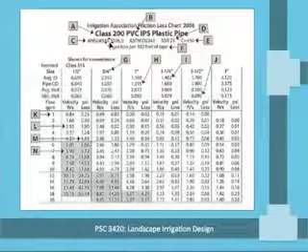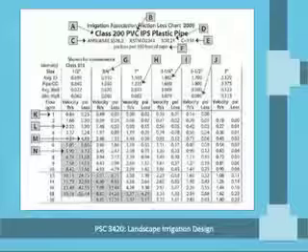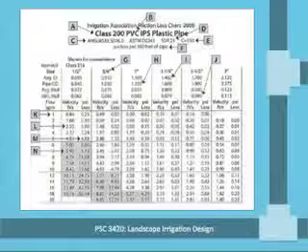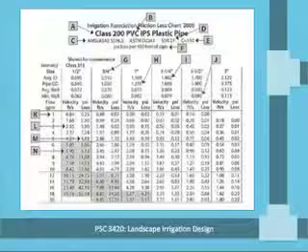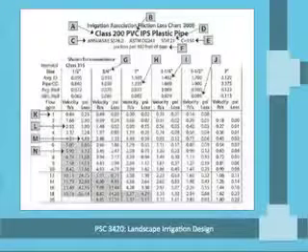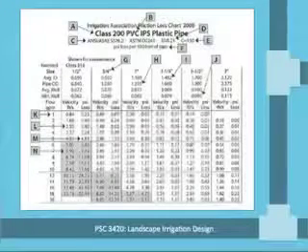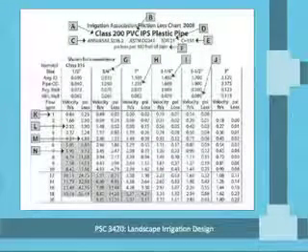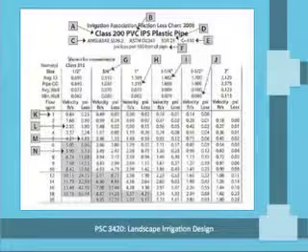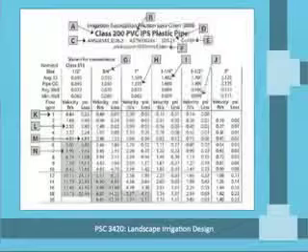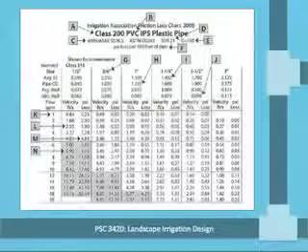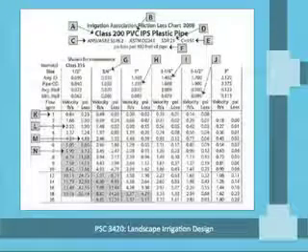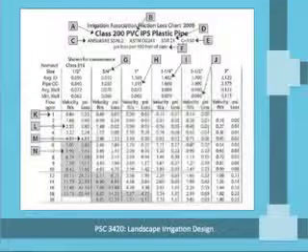C here refers to the standard by which the pipe is manufactured. So ANSI or ASAE standards, those stand for American National Standards Institute, and in this case ASAE stands for the American Society of Agricultural Engineers. D, SDR, or standard dimension ratio, indicates the pipe wall thickness as a ratio of the outside diameter. If you divide the outside diameter by the wall thickness, it will give the standard dimension ratio, or SDR. All pipe with SDR 21 has the same pressure rating of 200 psi, for example.